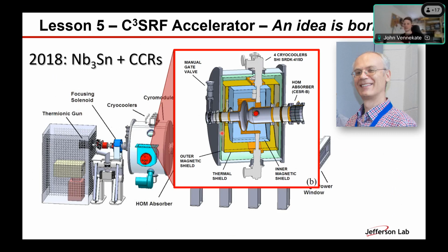So you really have a significantly higher power, and that makes this technology much more feasible for large-scale facilities with much more throughput, because you can deliver the same dose to your water and contaminants in a much shorter amount of time. There's a factor of 100 between the 10 kilowatts of the currently used technology and this technology going up to 1 megawatt.